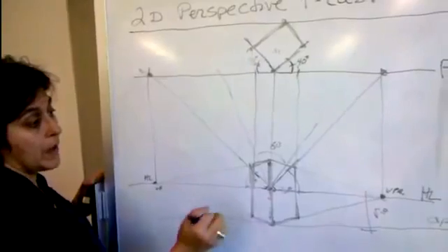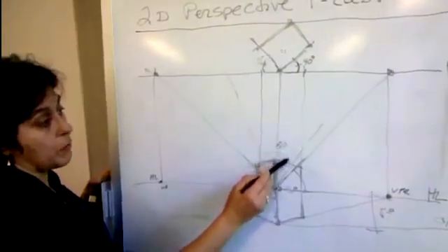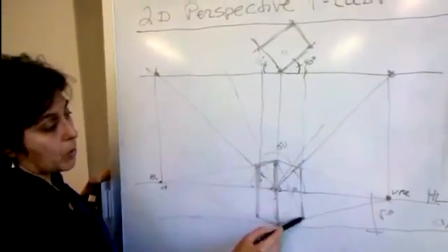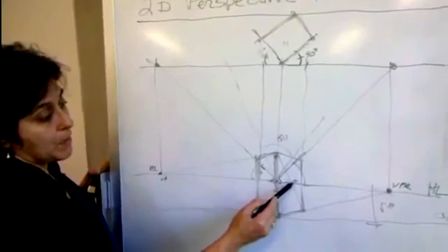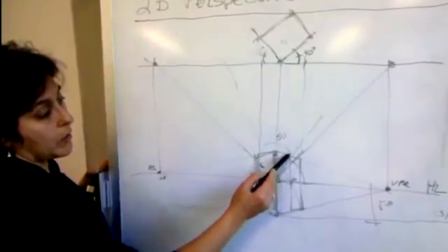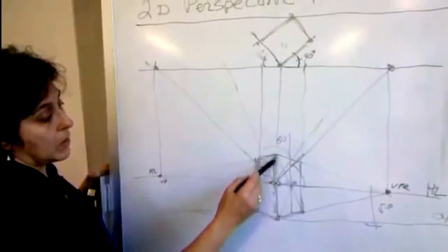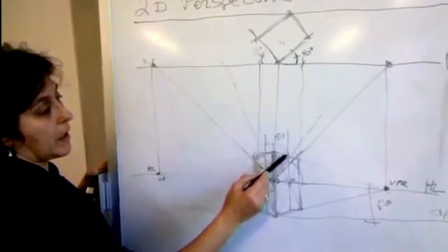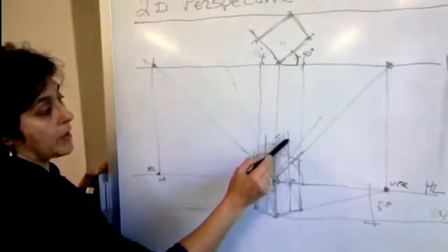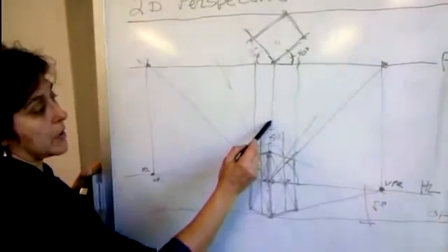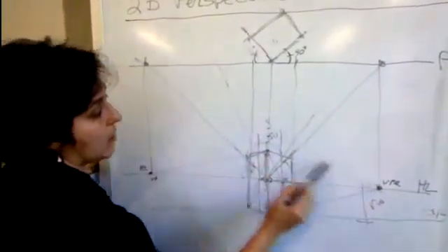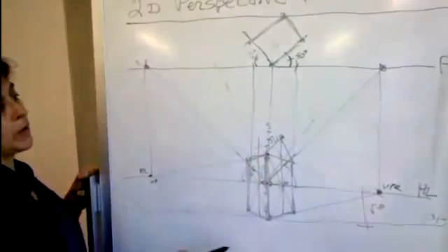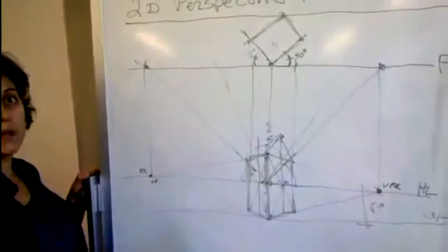To find the center point of either one of these sides, to find a roof peak or any other element, you can graphically draw from corner to corner. The point at which they meet is the center. You draw a vertical line through that. You can do the same thing on this face if you need to. Now, if you need to find the height of a ridge on this line, you scale along this line and come back down to that horizon line, and wherever it crosses that line gives you that exact height. You draw those lines, and you've described the gable end of the roof.